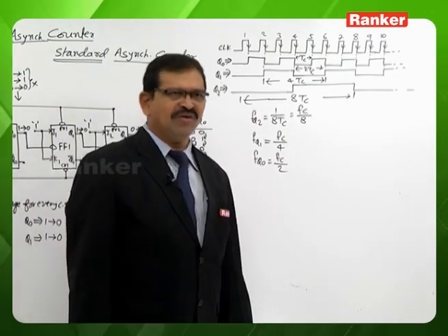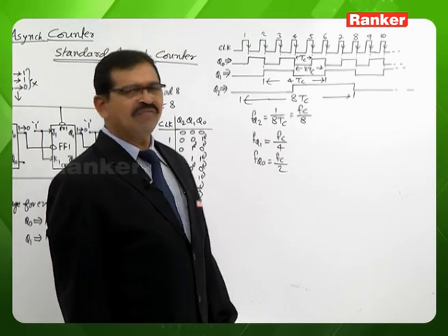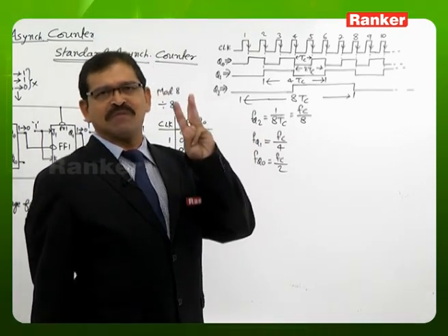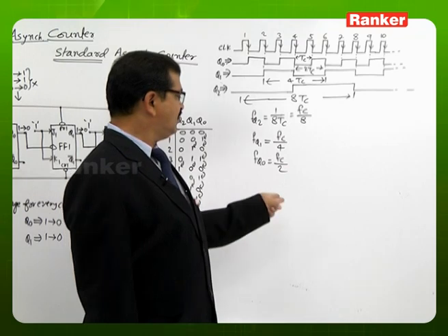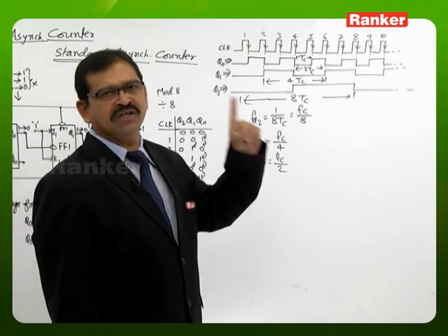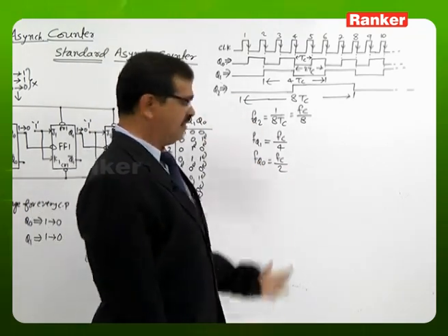In fact, if we want only divided by 4 operation, then we do not need 3 flip-flops, 2 flip-flops are enough. If we want the divided by 2 operation, then of course only 1 flip-flop is enough.